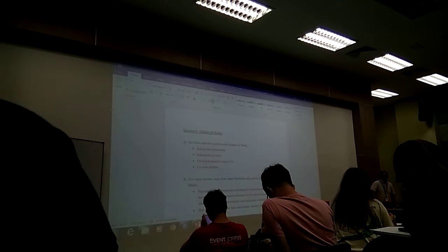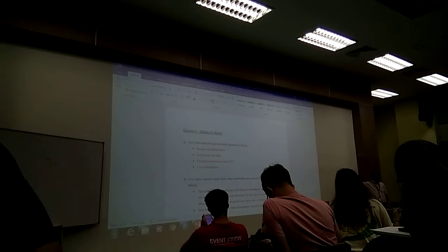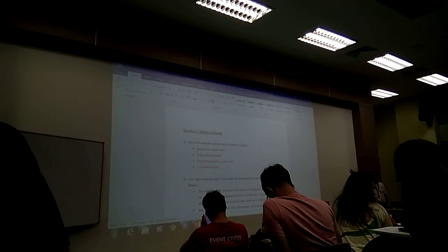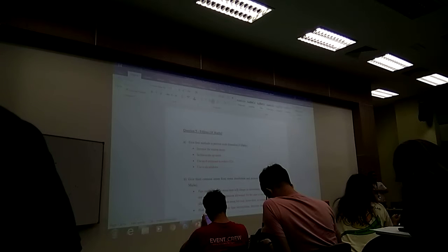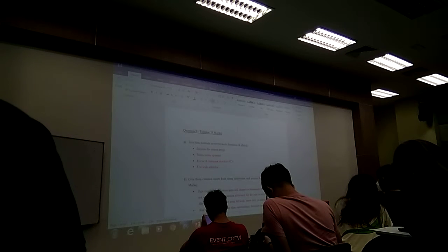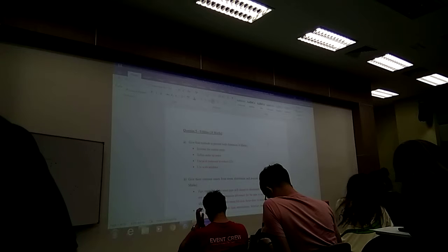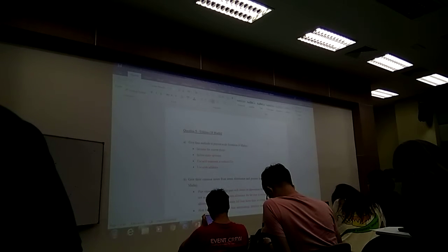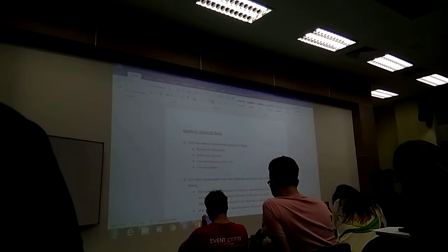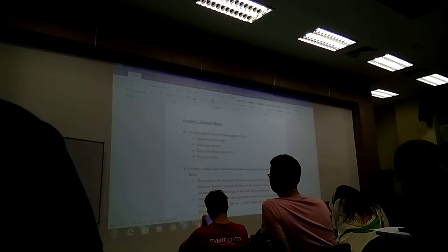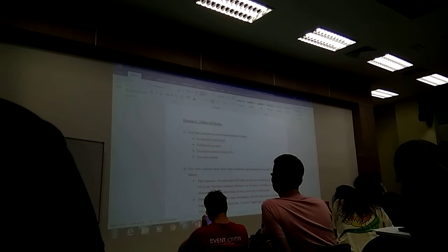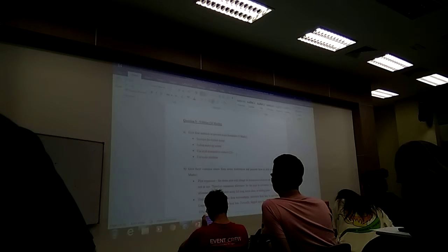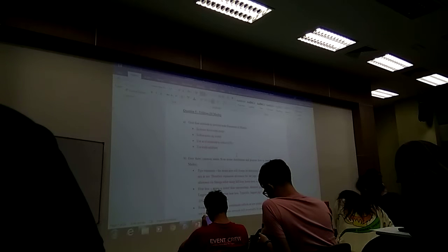Okay? So the questions on the utilities, my question on the utilities, the UC sometimes doesn't really, but because it's already mentioned, right? You will have theory questions on the utilities, so it will be maybe something like this. Give 4 methods to prevent scale formation, or definition, what is scale formation? What is the cause of scale formation? 4 methods to prevent scale formation: increase the purge, soften make-up water, use acid treatment to reduce CO3, use scale inhibitor.